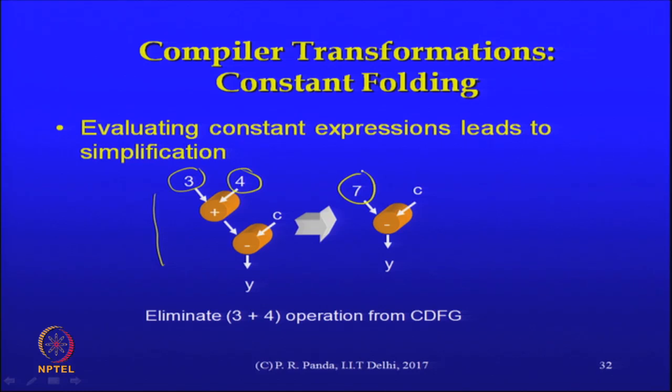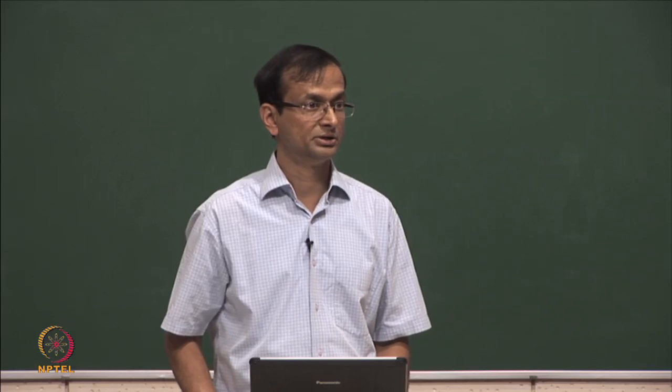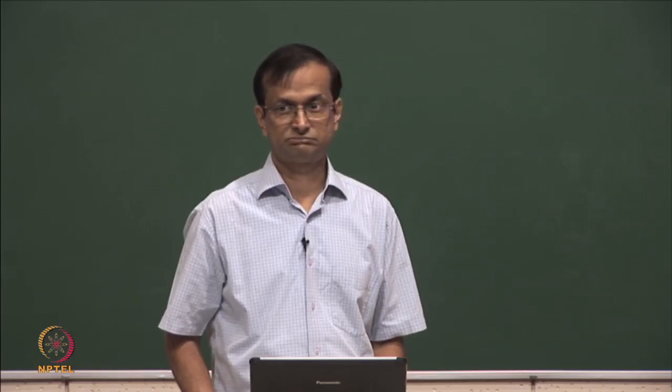What is the point? How does it help? Resources are being reduced. How? Normally it takes one cycle. Yeah, so this 3 plus 4, if I had not simplified it, I would have scheduled that operation in one of the cycles, which means that it is taking a clock cycle. That resource that is performing the addition, that adder resource, is blocked for this operation during that time period.